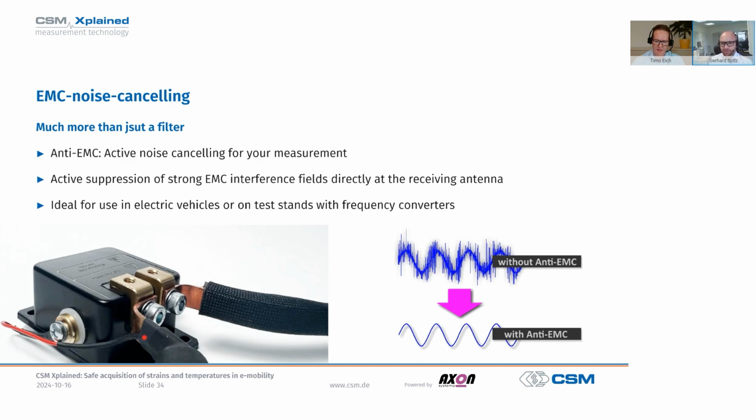But on the other hand, we have just a receiving antenna just for the surrounding, for the interferences from the surrounding. And then we have the two informations. We have the mixed signal on the one hand, and we have only the interfering signal on the other hand. And then we can start to calculate and try to recover the original data stream. And this is maybe something you can compare with on the acoustic side with those noise cancelling earphones. They're working quite the same.